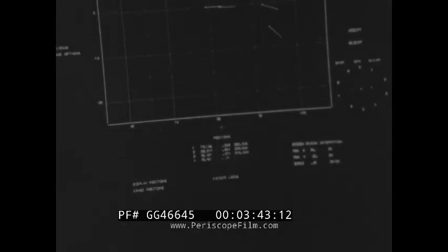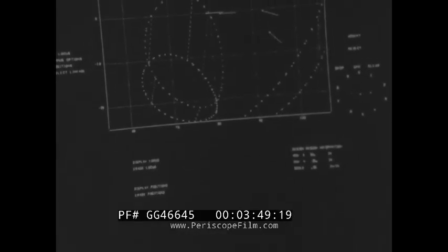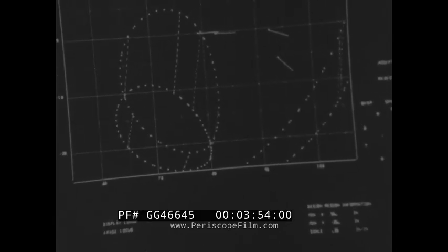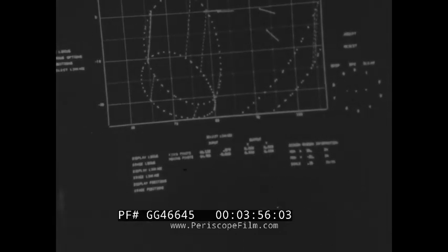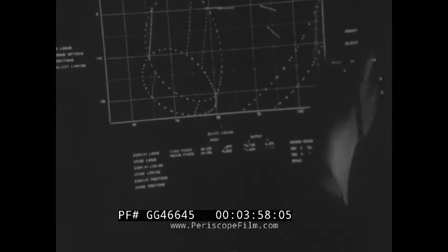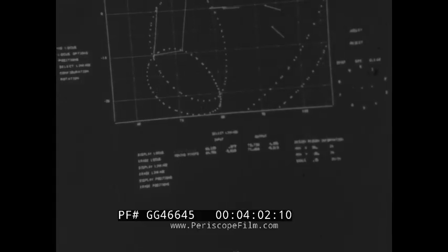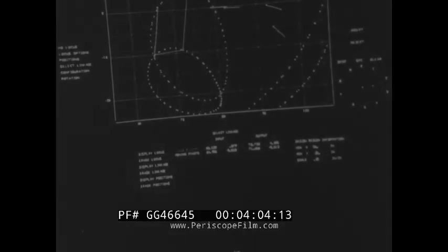To demonstrate the program, I shall select the first constraint option, 4-position coupler guidance. After defining the constraining positions, loci curves are calculated and displayed. These curves define the set of 4-bar linkages which will exhibit the desired motion. Linkages are selected from the curves by positioning the tracking cross somewhere along the fixed pivot curve and accepting its location with the light pen.